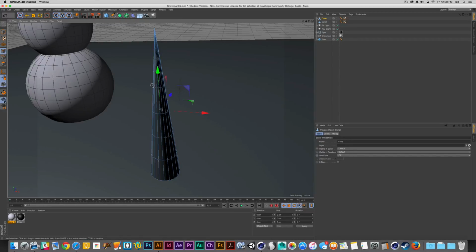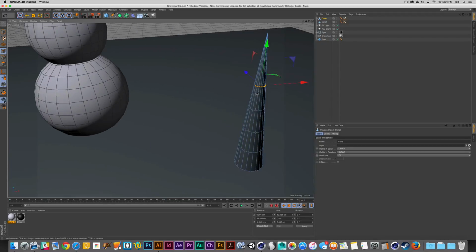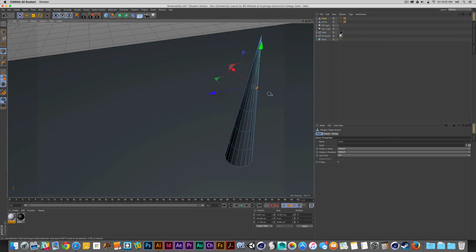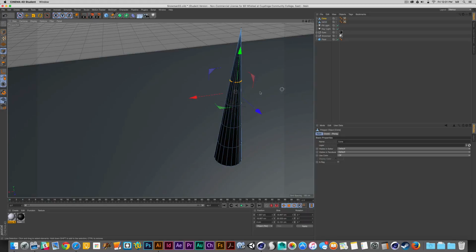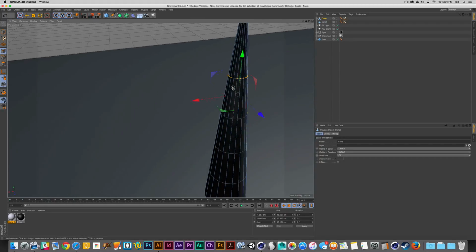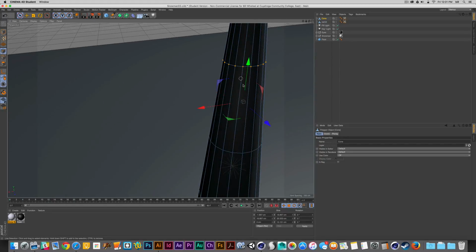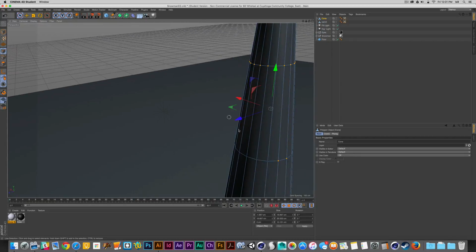Now I'm going to select around this object just by painting with the live select tool, and I'll hold down the shift key and start off in this workspace and click and drag back into the object. Okay, if I find myself in a situation where I over select some things, that's okay. I'm missing a point here. It's kind of hard to see, but I just missed that point right there. So I'll shift click and paint. But if I over select, I can on a Mac hold down the control key, I believe it's Alt on PC, and just paint back over the points that I don't want included.